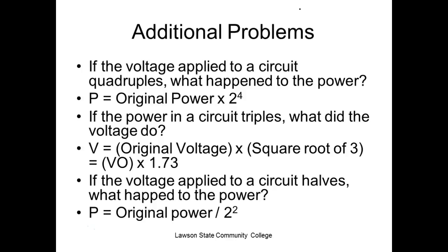On the Motoman robot, I don't care how you get to point 1, you have to teach point 1. So on the Motoman robot, you have to teach all three points. I think the ABB uses P1 as your entry, however you get to that point, and then your other two points.